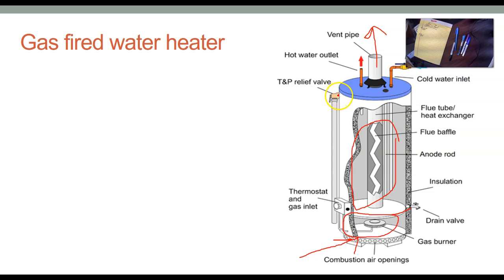All hot water systems are required to have a relief valve. This relief valve is usually rated at 30 psi. We're gonna write it down here. 30 psi. Another piece of information, 30 psi or around that for any relief valve, to prevent a pressure buildup. Those relief valves are tagged and tested probably every 2 years, and there's an expiration date on those valves. It should be attached to it.